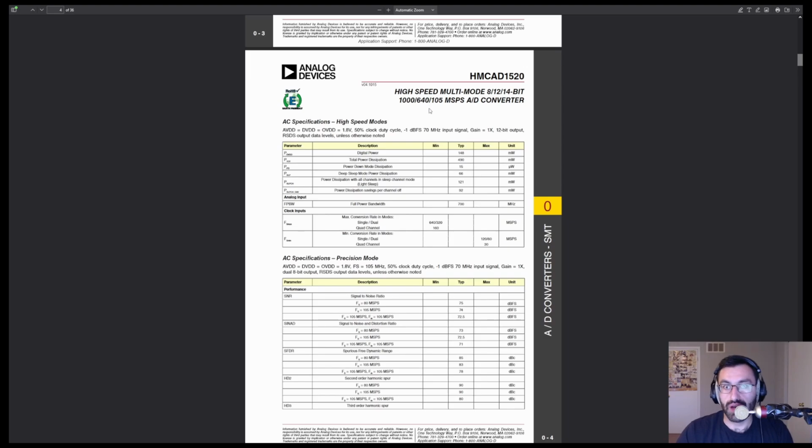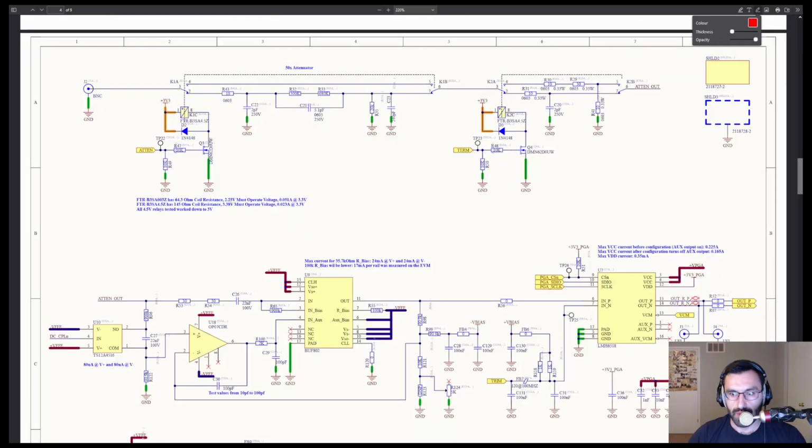Now, this doesn't stop you from sampling over Nyquist, which I will be showing you soon enough. But in terms of how you would use a normal scope, that's kind of your limit. So with all that talk about increasing the bandwidth, why would we ever want to reduce the bandwidth? Like everything else about this design, it's a trade-off. So the first trade-off here is in power draw.